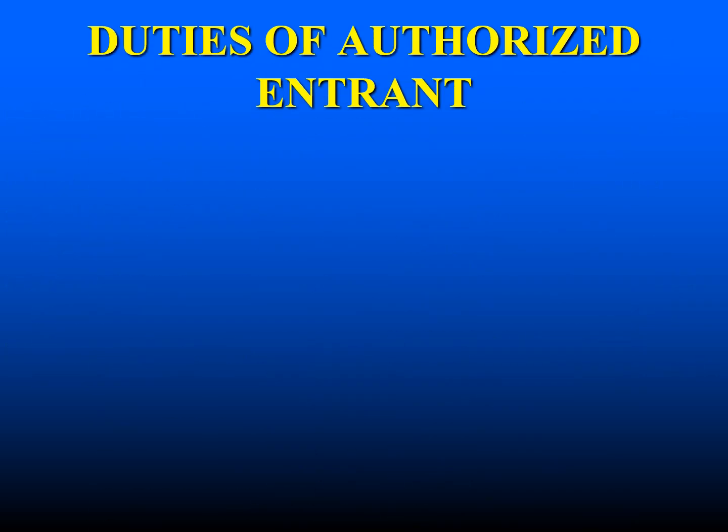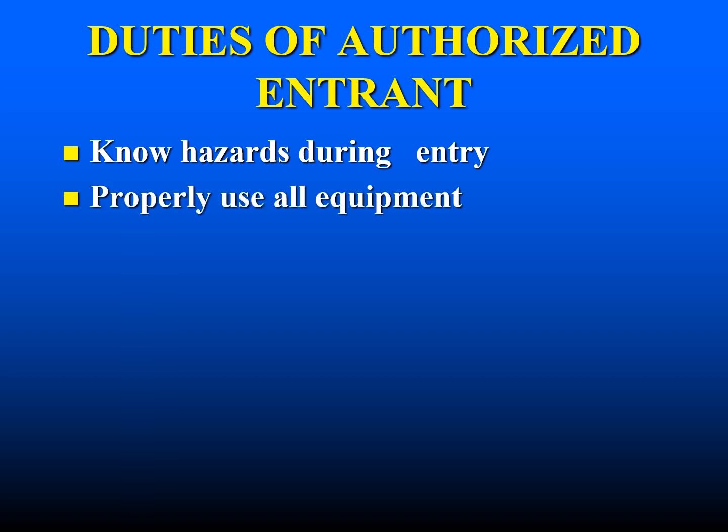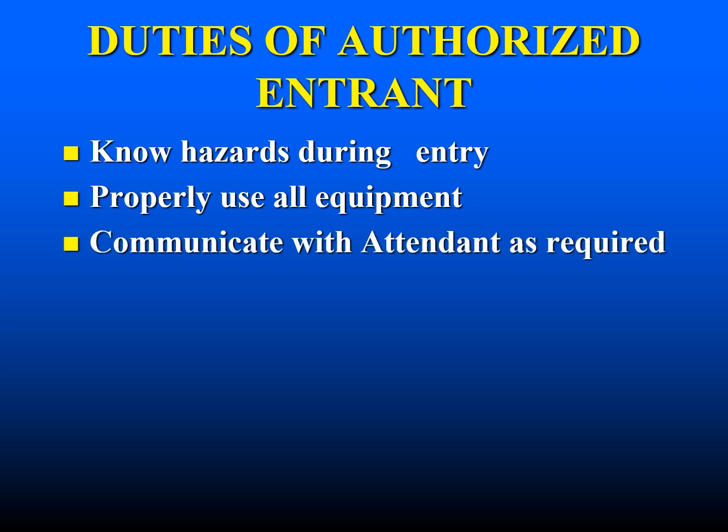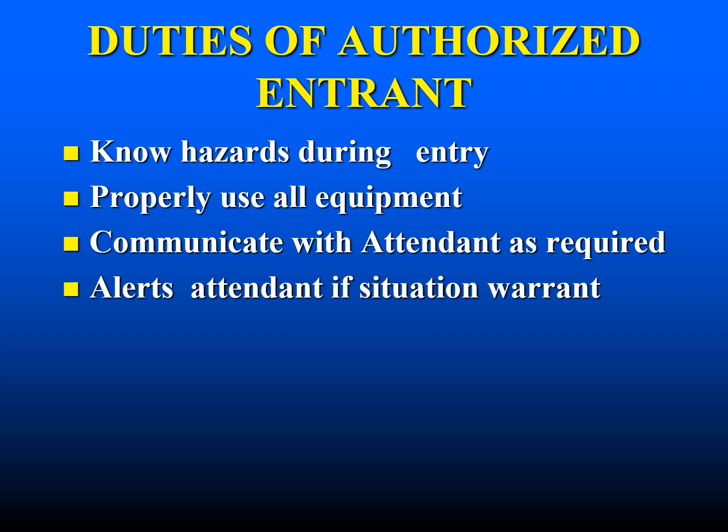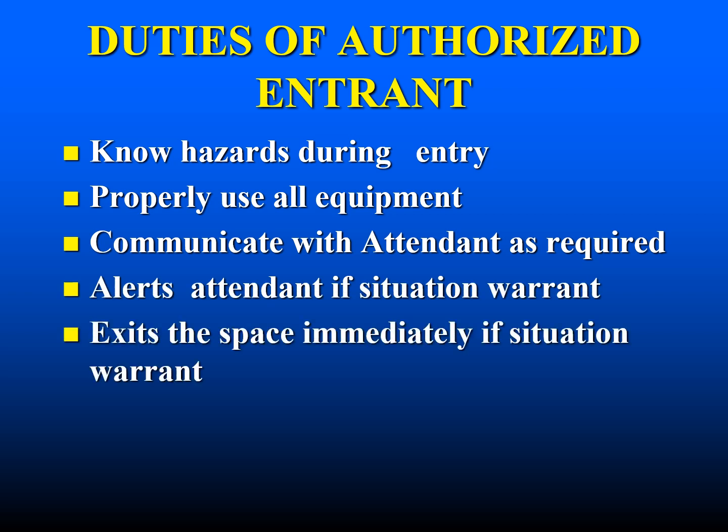The next position in a confined space operation is the entrant. So we just went over the attendant. Now we're going to talk about the entrant. The entrant must know the hazards during entry, and properly use all of the safety equipment and rescue equipment. They must communicate with the attendant as required, they must alert the attendant if situations warrant, and they must exit the space immediately if the situation warrants.